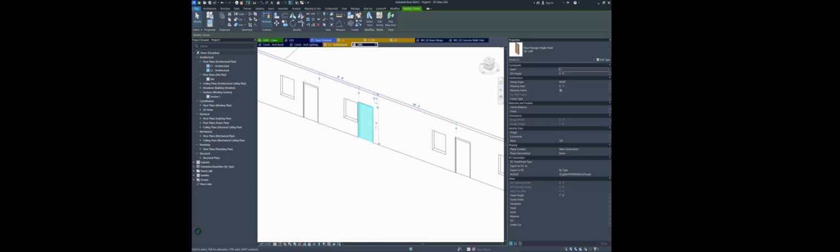I think you select the door and then click edit type and you add or use an existing parameter and then give that one door a unique value. All right, cool. You're getting warmer. So let me use one of these parameters. Let me use description, right? And I will just name it special because for whatever reason I don't want to hide this door. All right, and then what happened now?